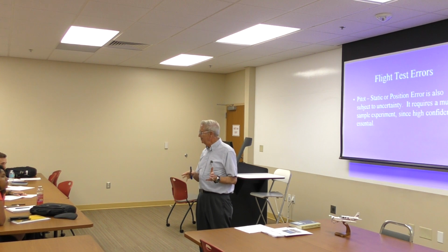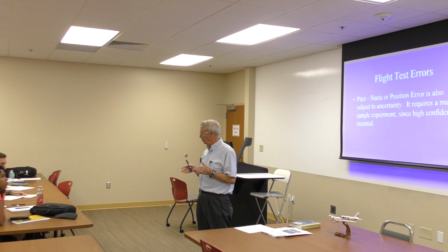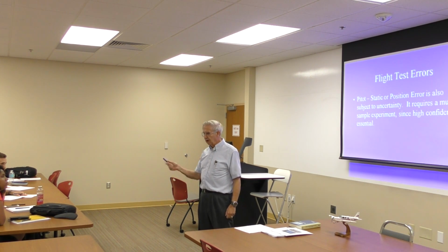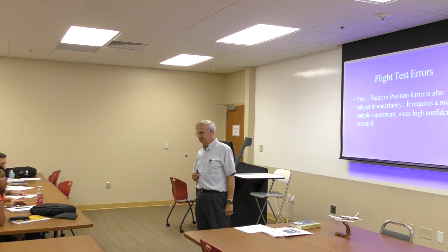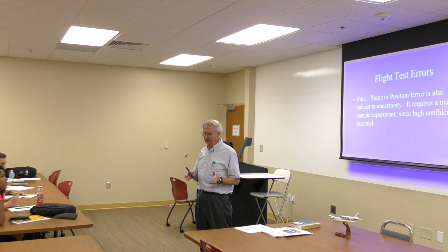They're all connected to the same pitot and static source. So you may see some differences, but those differences are not in position correction, they're in instrument correction, okay? But we will calibrate that system. It is going to be different than the one that I'll be flying off of.